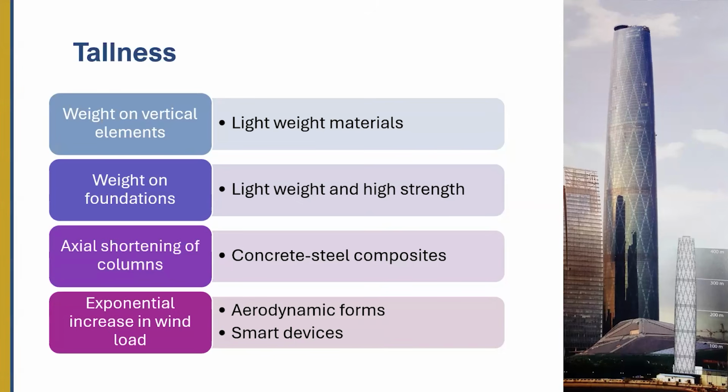Now, what will happen is that, let's say there's a column here and there's a floor here, and these two columns have different weight. And for architectural reasons or for uniformity, the size is the same because we can't change every column size. So that means one column will have more strain than the other because stress is different. Which means that this column will now become shorter and one column will remain longer, which means the building will now have uneven shortening of the columns.